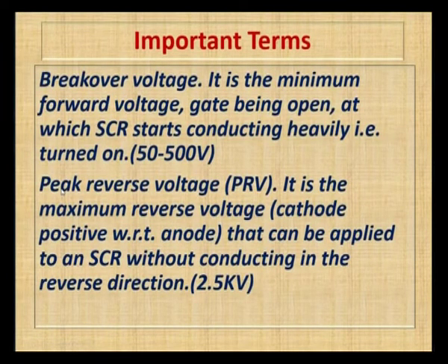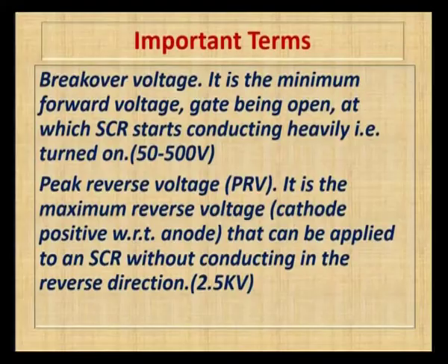If the peak inverse voltage is greater than the reverse voltage of an SCR, then in the negative cycle also the SCR is going to break down and conduct. So, this will lead to damage of the SCR. That is why we always need to note that the peak reverse voltage should be less than the reverse voltage of the SCR. What is it?